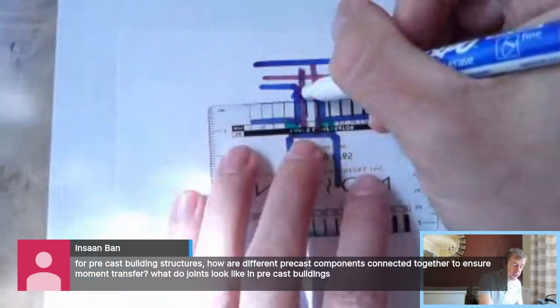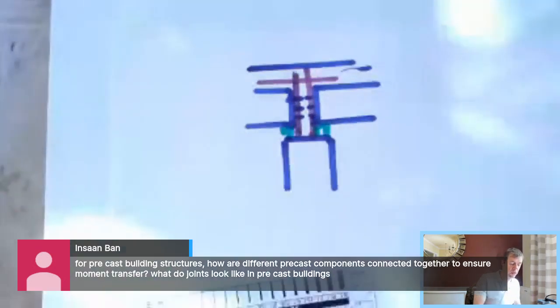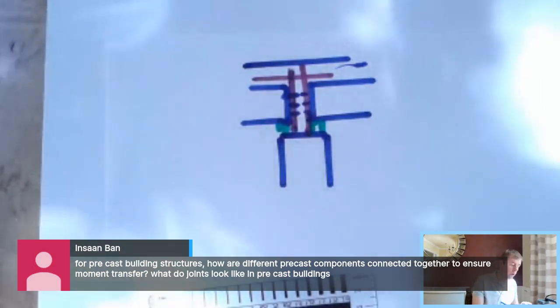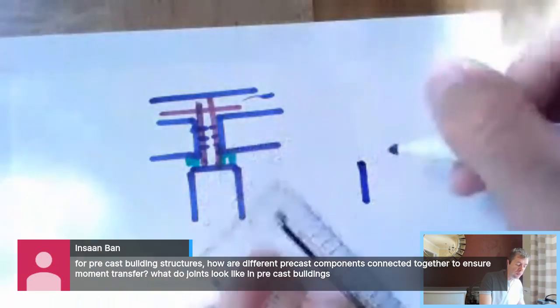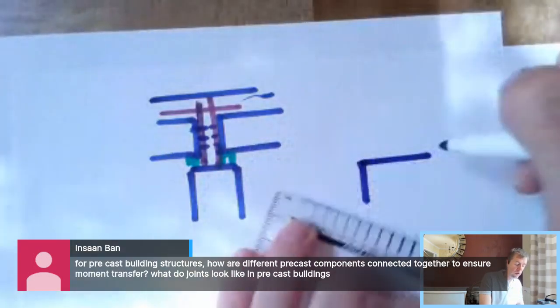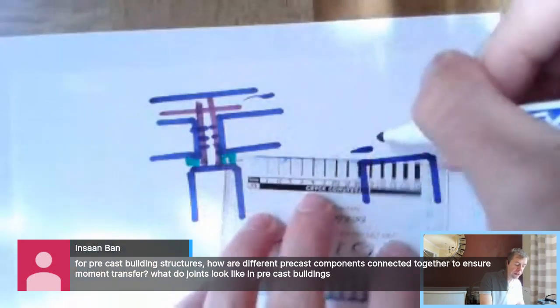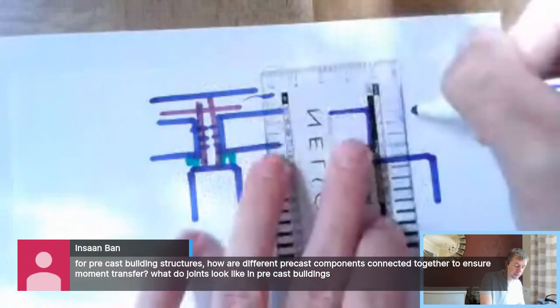You're also going to have steel that may come out of the beam that ties into this, right? That's something that you could do. Maybe you might say, oh, that doesn't look very good. Okay, I probably didn't draw it right. The point is that you maybe need to make your columns wider. You need to allow your beams, these are pre-stressed, precast, pre-made pieces.